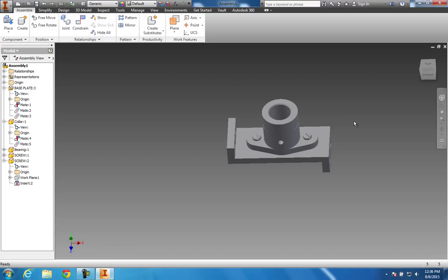But whenever you're working in assembly, make sure that you put all your parts in the same folder, and you put your assemblies in the same folder, and so on. Because if you scatter them out, and let's say, for instance, you delete one of them off, well, when it comes back to the assembly, you're missing that one part and it can't find it. It links out, and it knows exactly where all the parts are whenever you're building it.